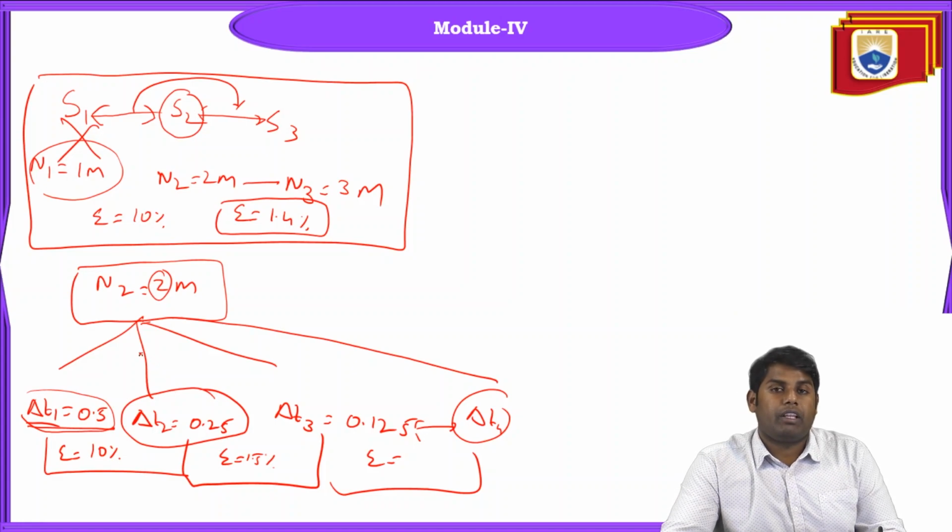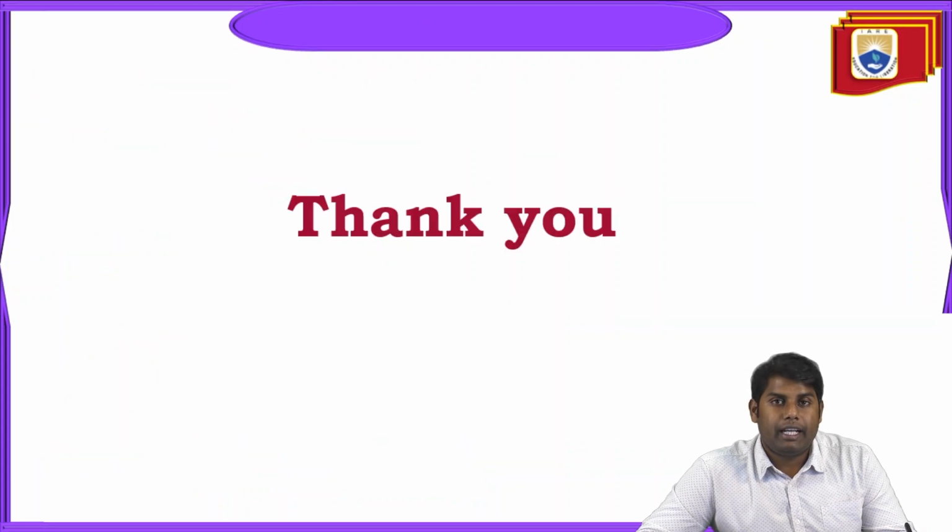With this, we have seen the basic importance of the CFL number. For the numerical schemes, the physical significance is that the CFL number plays a major role in stabilizing the numerical schemes, which in turn depends on the convergence criteria. The CFL also impacts the accuracy of the schemes. So the CFL number condition imposed for transient solvers is very important.